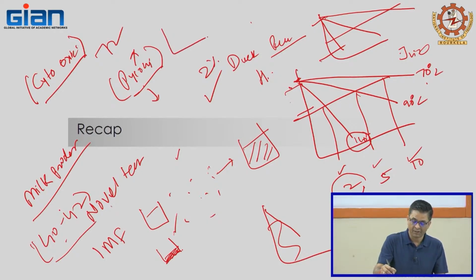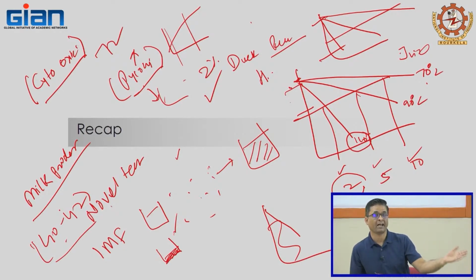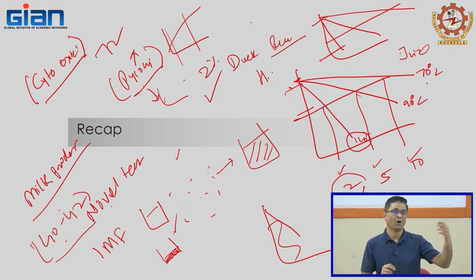Half the time, when we say conventional extraction takes 16 hours compared to ultrasound 10 minutes, it is because in the conventional method the first 5 to 6 hours only go in hydration of the powder. Freeze dried powder hydrates faster, hot air dried takes longer. If drying is done at 40 degrees Celsius, fewer nutrients are lost.